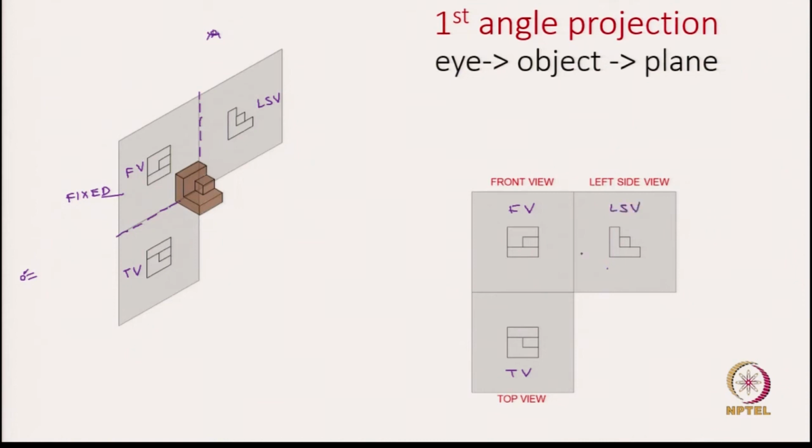This is why I keep saying that it is counterintuitive, because though we are talking about the left side view, we place it to the right side of the front view, and when we are talking of the top view, we place it below the front view.